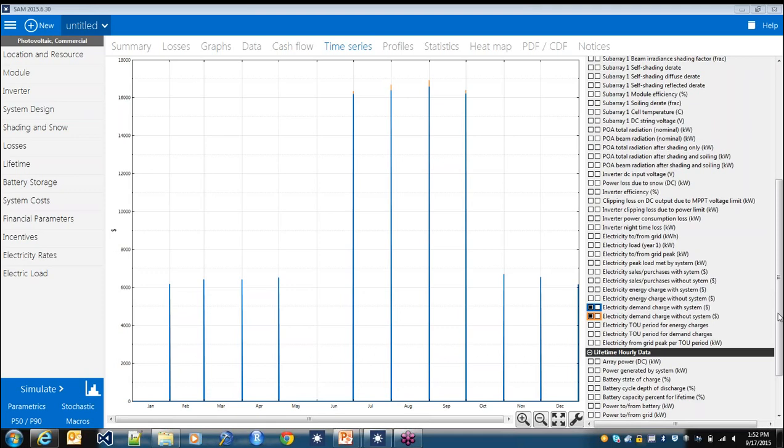Okay, so there's a question: what if you want the grid as a backup only, so that you really want 100% solar and battery, but not a true off-grid system? Basically, in that scenario, I think you're saying that you would want to be able to turn the grid on in certain scenarios, but not use it to meet the load. So I think in that case, you really just have to size your PV system and battery appropriately given your electric load.